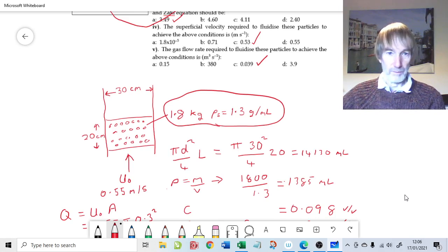So just to recap, if we increase the fluid, we would be expecting the bed height to increase nice and uniformly to this value of 0.902 for the voidage, which is what we were asked to calculate. But there is a possibility that gas bubbles could actually form here and shoot through the bed very quickly, and therefore the real bed expansion might be less than what we've predicted.